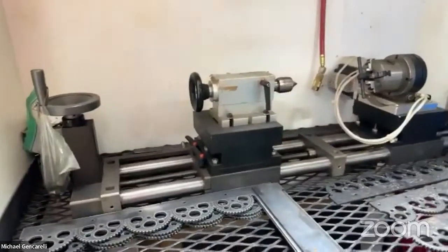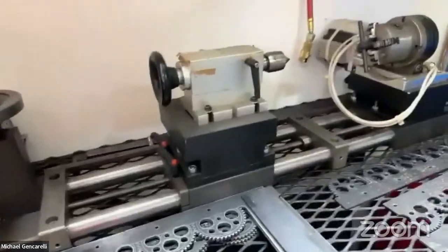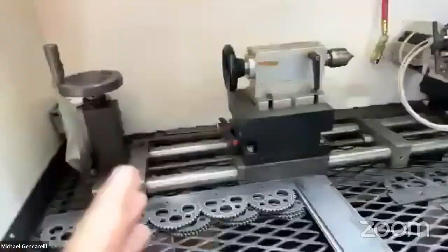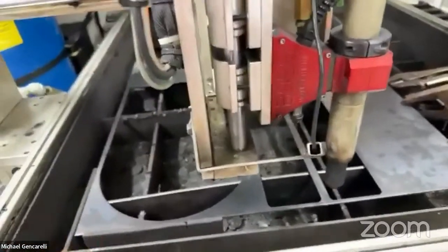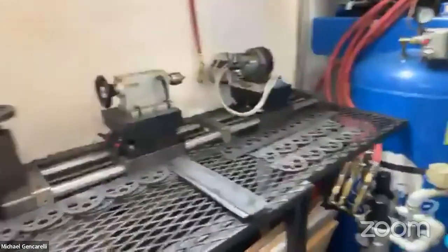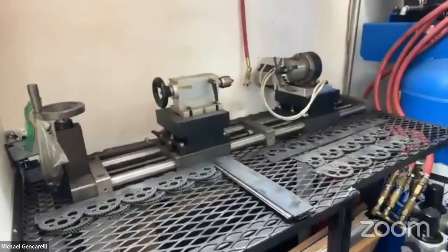When I want to do 4-axis, I've got a 4th axis on a self-centering slide. So when I crank the handle, these separate and come back, and they're always lined up. The stuff in the water table comes out, and then that goes in and gets bolted down. Now I can do 4-axis routing.